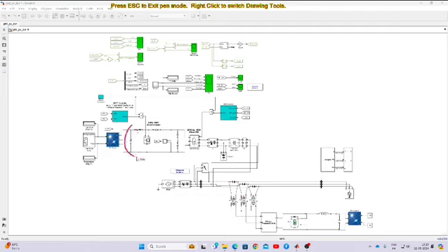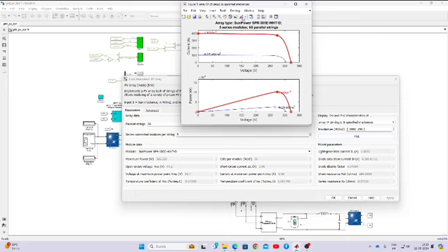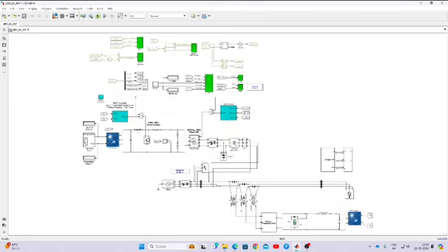It is going to be operated at 5 kilohertz, and it is going to boost the voltage to 500 volt, so here we have to maintain 500 volt. The input voltage, as you will see here, is around 273.5 volt, and after boosting the voltage will be changed to 500.